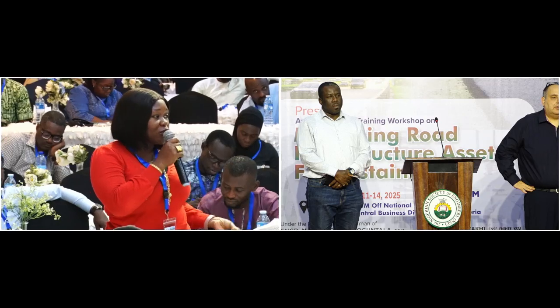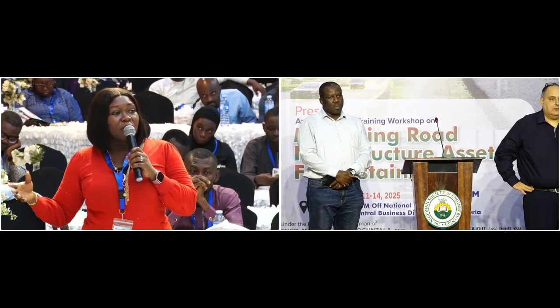Not a question though, but in all of this, I think quality control is very, very key for every engineer. Because if you do quality control and keep data, like he said, if you're using aggregates from a particular source, you have to go and check it. The properties of these aggregates, you do the sieve analysis, water absorption, specific gravity, all of the tests, and then you put it down. Now your asphalt too, you have to test it to know what's the penetration grade. Is it okay?